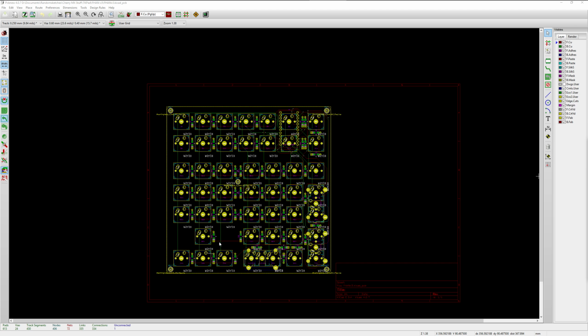Now, when we get to around some of our areas of interest, such as the compatibility section, you can see there's some crossing over and routing. If I select the routing, the trace tool, it highlights, and you can see that we're connected to 2 switches on that diode, but the actual pathway for the diode to complete is only connected to 1, because it's just using that same one diode. And similarly, our column is actually just running straight through all of those components. So it doesn't really matter, regardless of what's being in there or not. In theory, it should just connect all the way through.